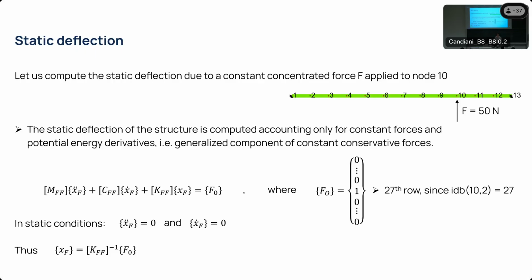So, for example, in this vector you could place the weight of the various elements. Of course, remember that you have to compute how the weight of each of the elements transfers to each of the coordinates, but we will go a little more in depth on that in the last lecture. But so you compute the external loads, which again can be cars, or the integral of any concentrated or distributed load along the length of the structure.